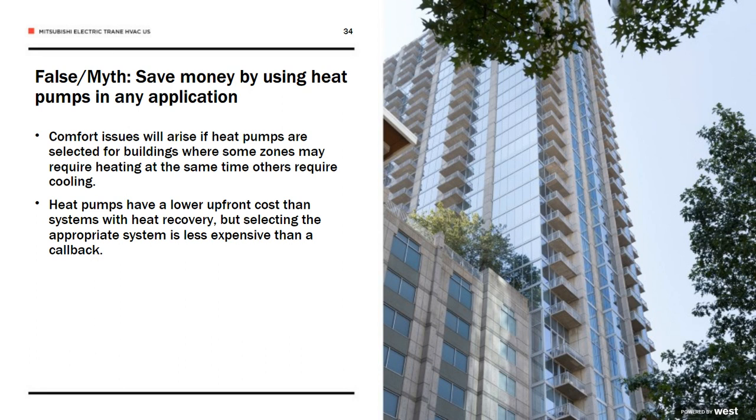You should use heat recovery. There is a premium to do that. So if you decide, hey, listen, we're going to try to do it, there are some strategies to apply, but at the very minimum, you want to apply a heat pump where you're going to have all heating and all cooling independent of each other.